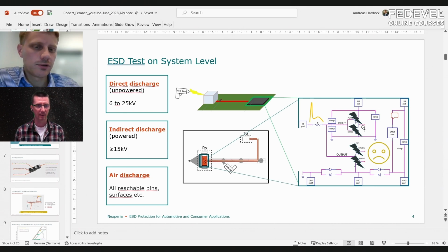They are sensitive, because even the internal clamp needs to protect very sensitive transistors with a very thin gate oxide. The voltages are very small, which is why you need to go to lower voltages on the on-chip clamp. That's why we react to this low voltage with low-voltage external ESD protections for high-speed devices. This is all connected.